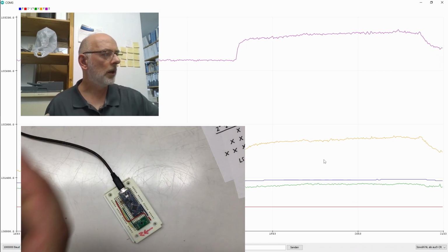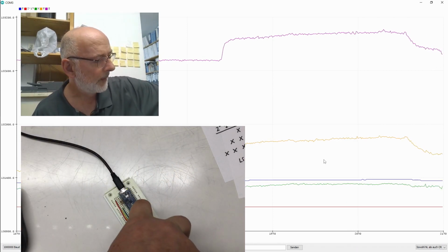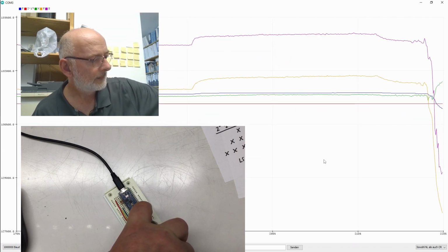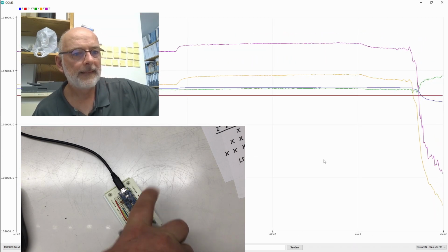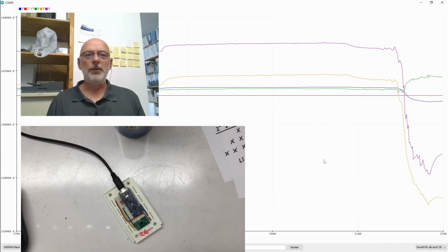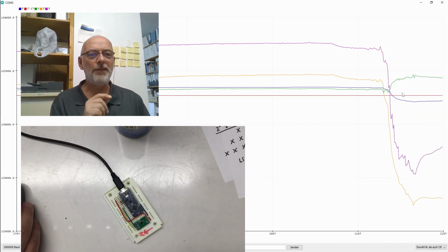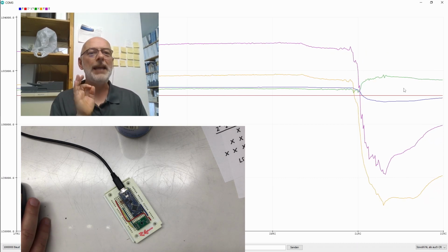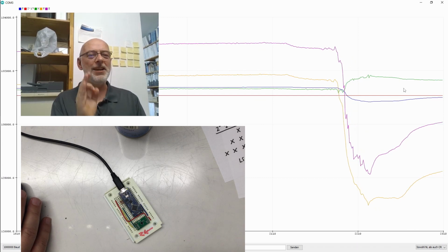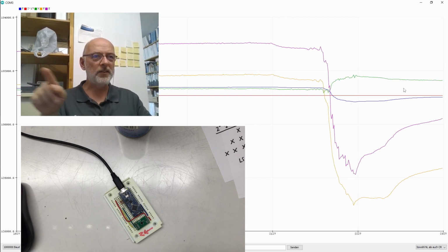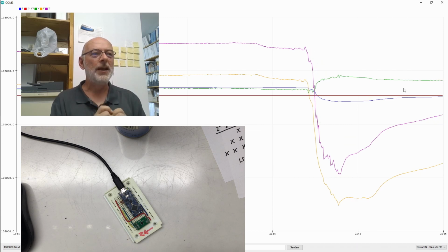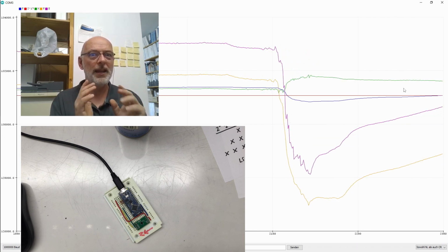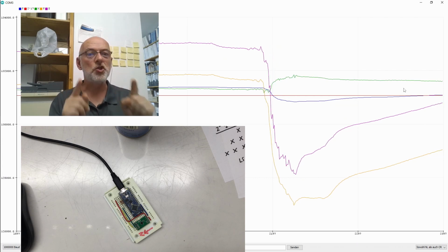And if we cool things down a little, you see the changes in offset are actually enormous. So temperature compensation for those Wheatstone bridge AMR sensors is a real thing. Well, a necessary thing if you want to take precision measurements.